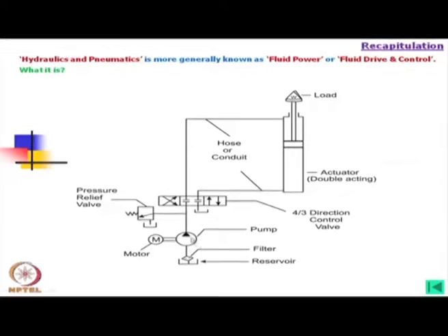hydraulic components. Suppose this pump is a hydraulic pump, and if it is a pneumatic pump, you can use a similar symbol. Only in the case of pneumatic, this triangle is not filled. Just 3 lines are there, and inside it will be white or blank. So, that indicates pneumatic. Similarly, pneumatic valves look more or less similar, but they have some special symbols attached, by which we can understand this is a pneumatic valve. But here what I have drawn are hydraulic components.